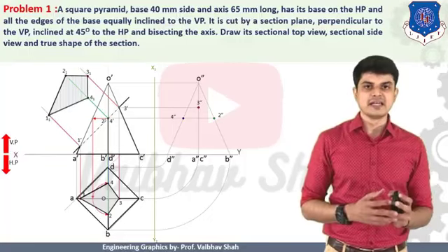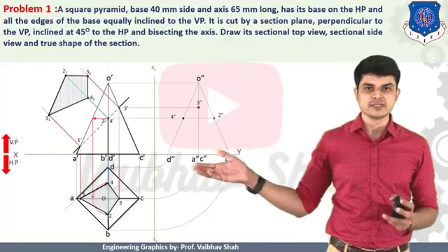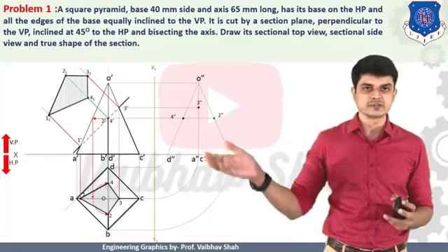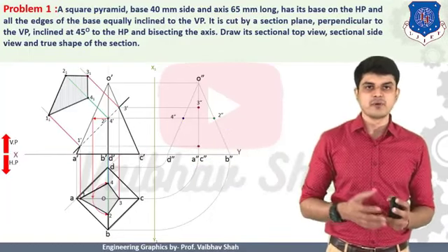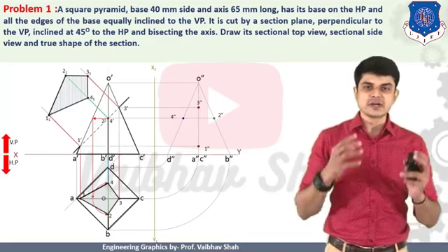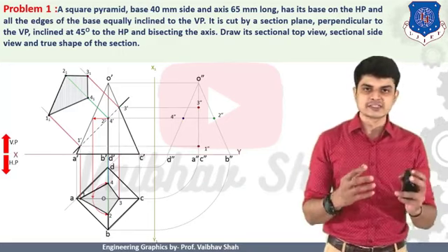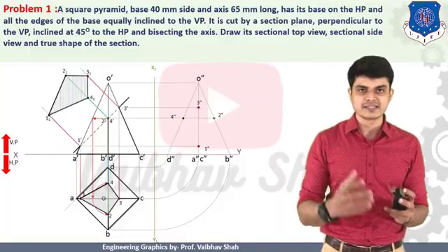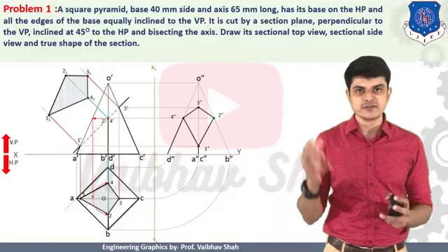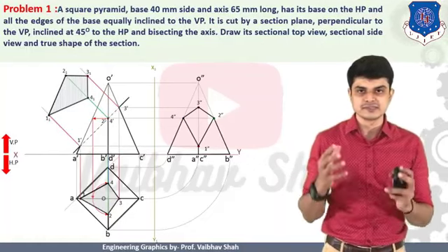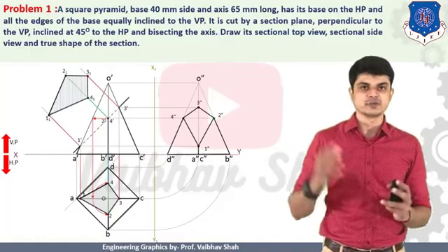Right? Then after, finally you should have your point number 1. Point number 1 is on the AC line. So when the AC line goes up, and if you draw the horizontal line from your point number 1, you will have your point 1 double dash generated somewhere here. After getting all of these points, let us connect these points by a darker line. So we will be connecting all these points, and then after, we should just finish the object by a darker line. So this will be your final cut section in your side view.